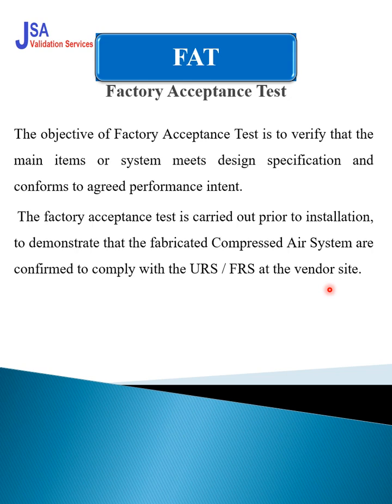Then you test as per the protocol. If required, you have to ship the material. In the case of equipment, you can also ship raw material or packing material to the vendor, for a compression machine or any other critical machine. Then you can challenge with tests like IQ, OQ, PQ, which we commonly perform in the factory acceptance test in the same protocol, so we get an idea of how the machine will work.